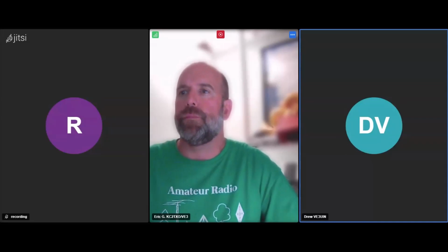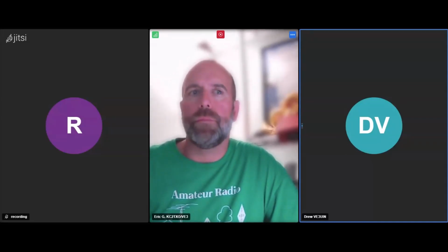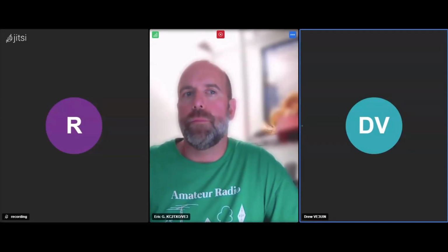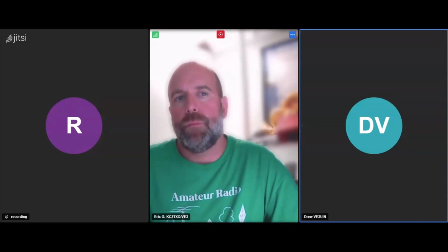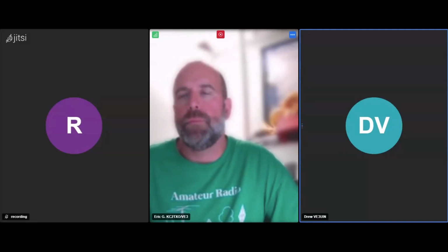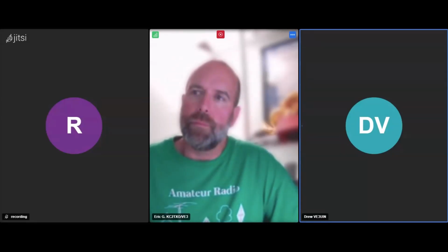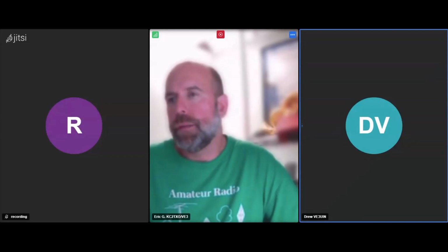on one end. It has 102 feet of copper that is mounted so that it's got a triangular section. So it's basically an apex of 40 feet and 102 feet separated, so 51 feet each side of the apex. Okay. You have a 450 ohm resistor on one end, and you have the 9-to-1 on the other end. And so you have the antenna in a triangle, a delta configuration, and then you join the ground to the ground of the